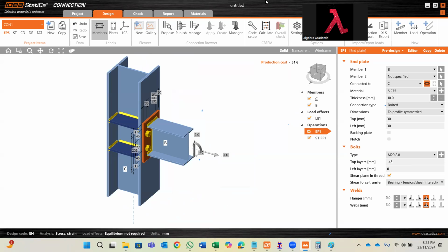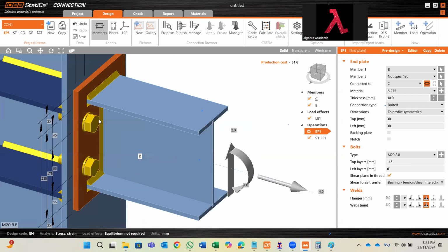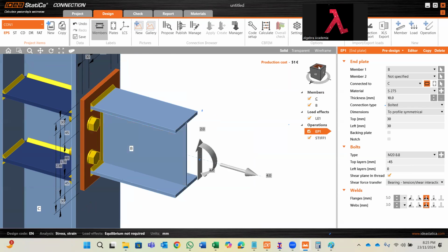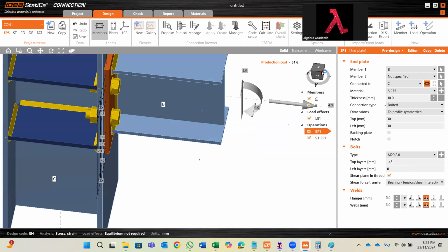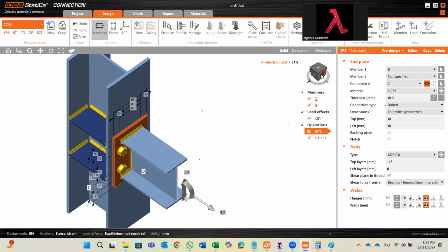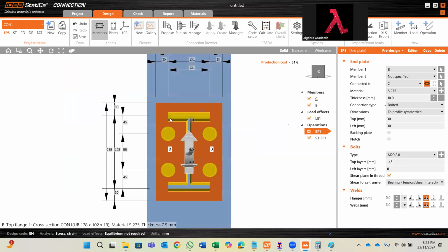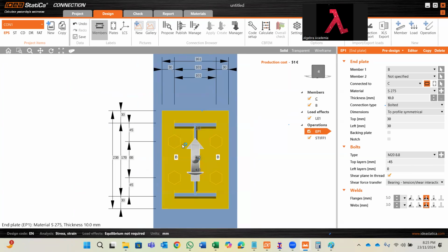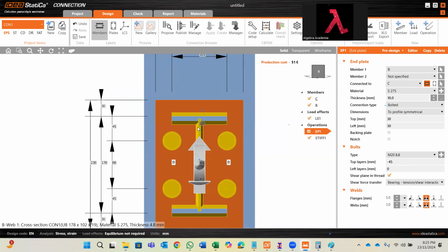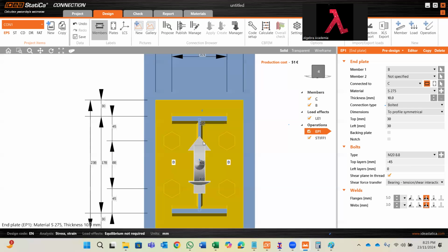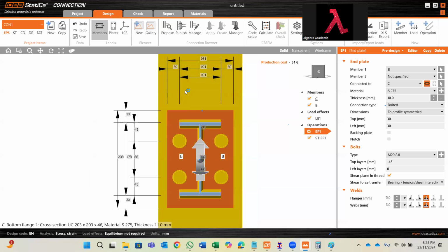Okay. See, I'm keeping 35, 70, which is very close. So I try this, which is very close. Okay, because you need to count the web thickness as well. The web thickness will be 10 millimeters. Okay, so if it is 60, it will be very close. So what has been taken is almost 101 millimeters. Okay, 101 millimeters. And keeping the edge distance at 30.